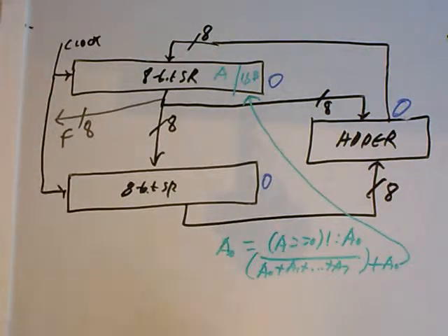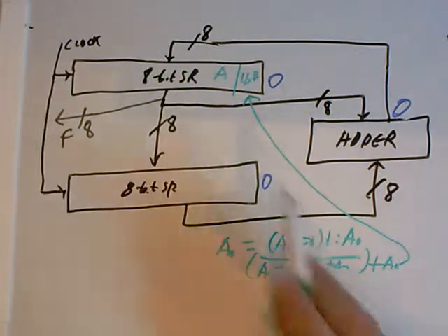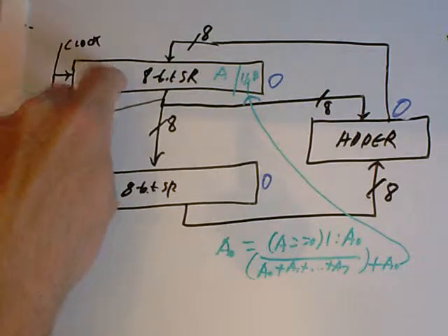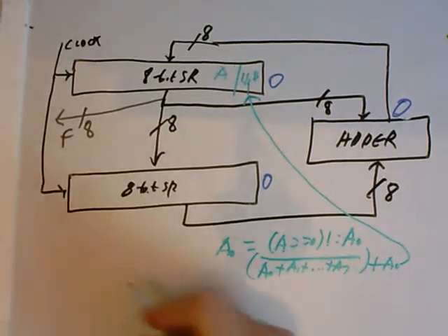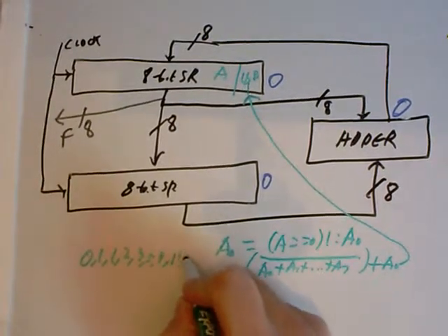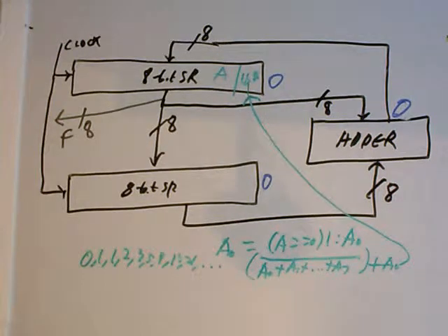And that will be the bit that I actually send into here. So now if the value coming out of the adder is all zeros, this will be a 1. It'll get ORed with the least significant bit, and then my A register will be initialized to 1. If anything coming out of the adder is a 1, if the value is non-zero, then one of these will be true, this will be false, and the least significant bit will not change. So we'll build that circuit also to seed this automatically. So when we first load this circuit into the simulator and everything is zeroed out, the first value that we load into this register will be 1. So that will start our sequence at 0, 1, and then it'll be 1, 2, 3, 5, 8, 13, 21, and so on, hopefully. So that's the basic setup.